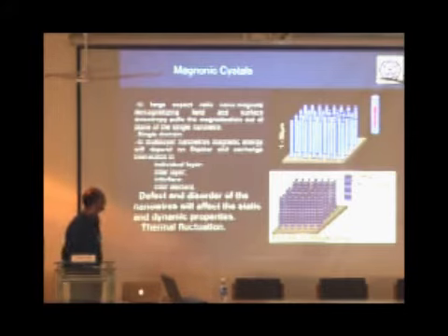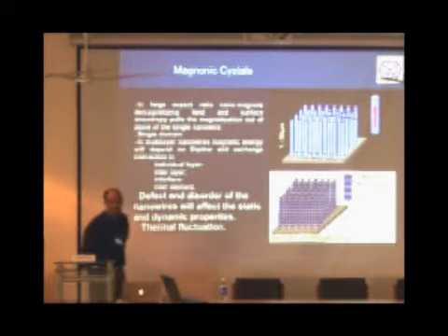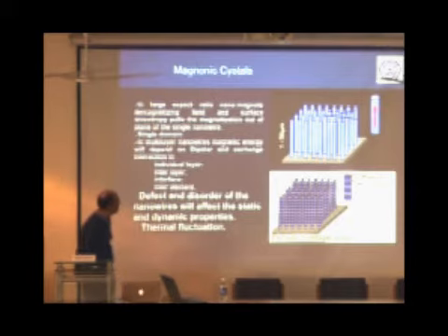These are essentially pillars of magnetic materials, typically cobalt chrome platinum when I use hard magnetic materials, or nickel oxide for antiferromagnetic or cobalt materials. We try to make nanowires arranged in regular arrays. The regular arrays are usually made by lithography, essentially nanoimprint lithography or E-beam, and the irregular or densely packed arrays are made using alumina templates, using electrodeposition.